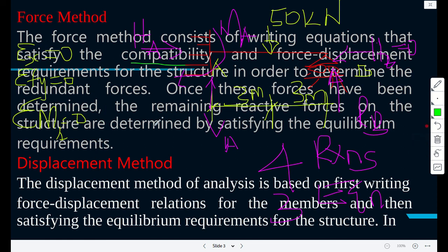So you will remove the support at B. Probably there's another way to do it, but you find this the easiest way. If you remove the support at B, then you're able to solve with the 50 there. Then you can solve the reactions and then replace the support with a reaction at point B. And this equals this plus that. So this is statically determinate, and this is statically determinate. You can solve each at a time.